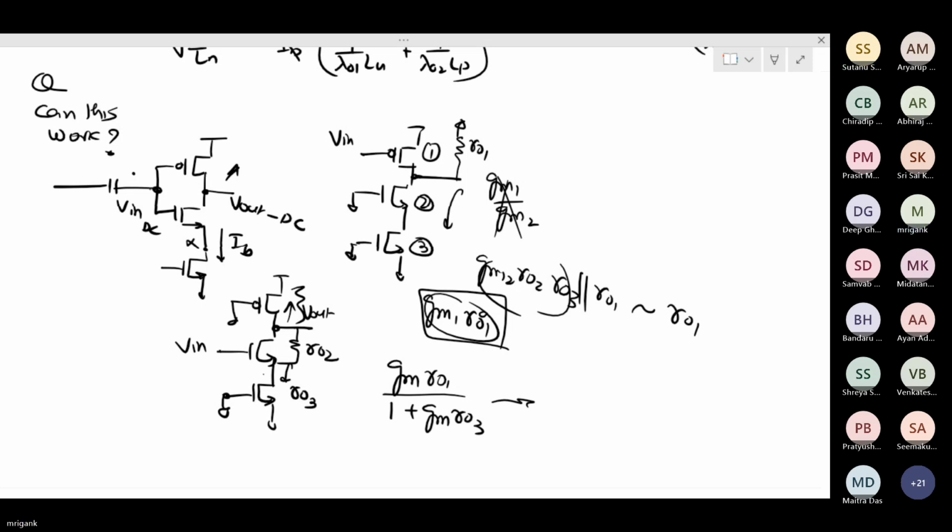Yes, sir. In case you have capacitive coupling, you can't even solve for Vin. It's a floating node. Some random value will come based on the gate leakage, source leakage, whatever. It is not solvable. Ultimately, in the actual circuit, it will acquire some value based on the leakage current. We have not considered leakage current so far, but there is gate leakage current from PMOS and NMOS, and the capacitor will have some leakage too.